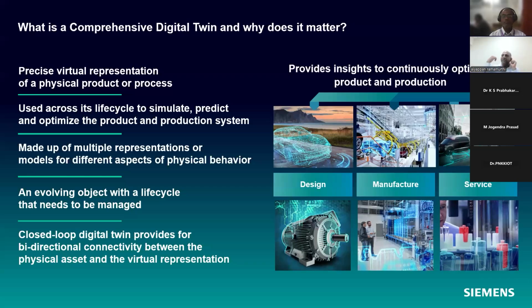As I told you, I can have a twin of my fan also, but by having this twin, what problem is it going to solve, right? In a year, maybe there is a failure, or it may not even be a failure. And even if there is a failure, I can get it repaired. The downtime is not going to cost much, the replacement cost is also not very high, and the criticality is also not there. Then the reason for me doing a twin of the fan possibly is very limited.